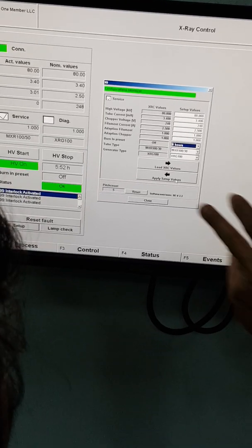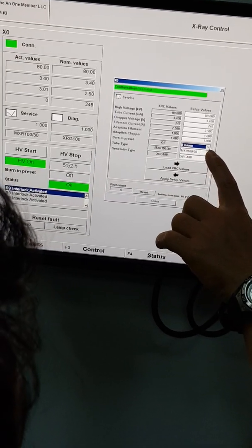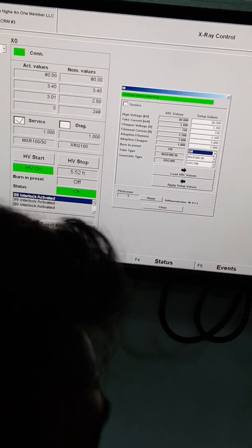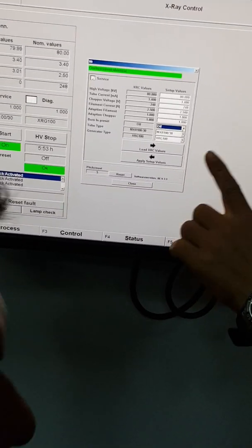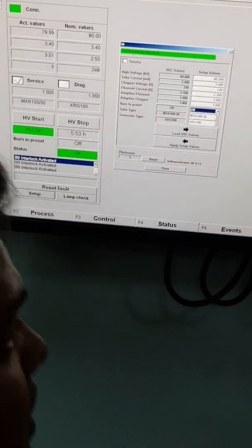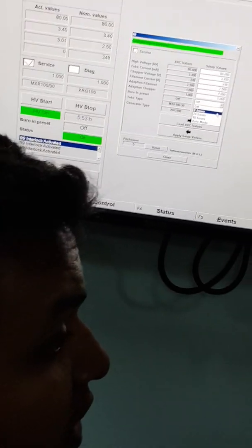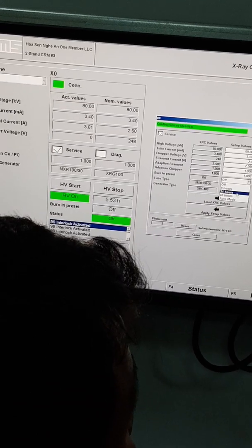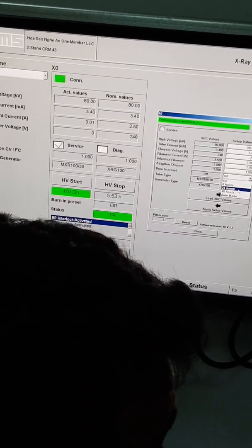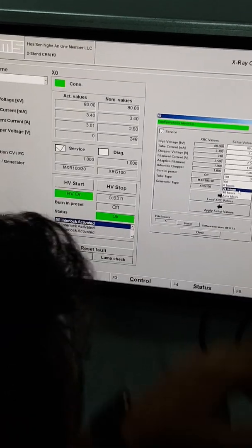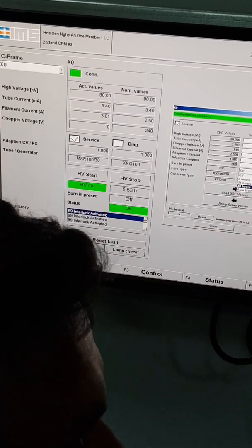Here you can set 24 or more. Yes, of course you can set 24. That's what I'm telling you. If the HV is off for 1 hour, you put 8 hours. If the HV is off more than 3 hours, you put 24 hours burning. If it is more than 5 hours, you always put 48 hours.